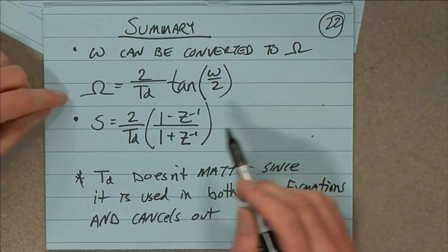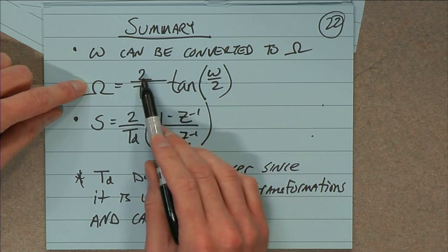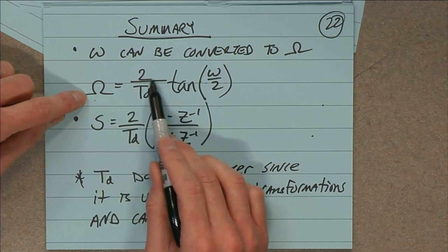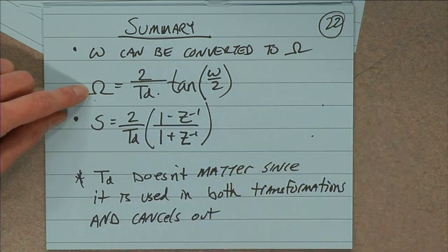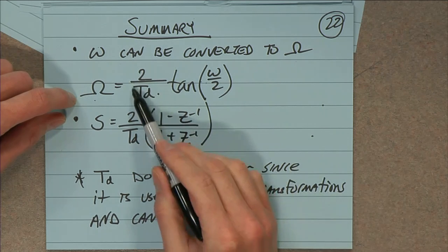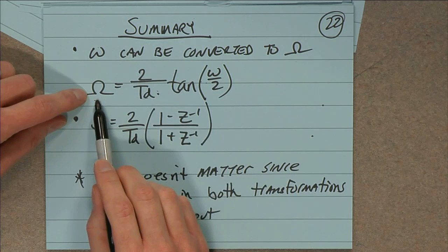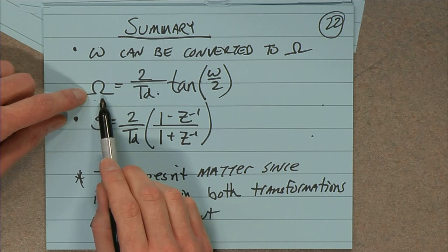So your first step is to apply this formula. You take that pi over 4, run it through here, and get some omega out. You had to apply some TD to do that. Then you turn the crank and get H(s). Now in your mind you can think H(s) does have some relationship to this TD, because H(s) depended on this. And we're going to see how that happens with the Butterworth in gory detail.